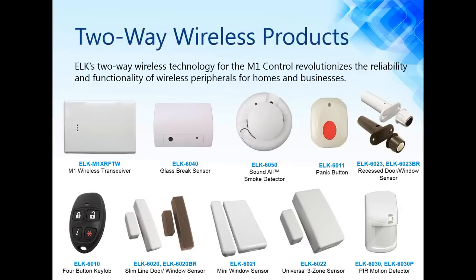We have our ELK 6050 smoke detector, and we call it our sound all smoke detector. It has a built-in sounder, and if the detector goes into alarm, it sends a signal to the M1, which sends a signal to the other 6050s to start sounding as well. So all of your smoke detectors would go off at one time with their built-in sounders. Now, if the M1 goes into alarm, let's say from a hardwired smoke detector or a fire panic on the keypad, again, all of the 6050 smoke detectors would go into alarm and start sounding at one time. I don't believe any other wireless technology incorporates that feature. So it's a wonderful feature for the M1 system.